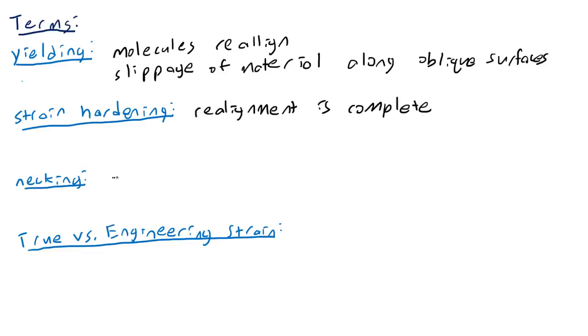And necking is local instability. What happens is the material starts rapidly thinning, and as the cross section thins, that increases the stress because there's less surface area in the cross section, so that makes the stress go even higher, which means it thins even more, and the thing quickly just essentially collapses, or pulls apart, I should say.